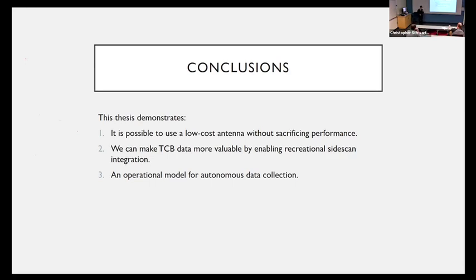We demonstrated that we can make TCB data far more valuable by integrating a side scan component and providing the opportunity to generate images of targets on the seafloor instead of only collecting single beam soundings. And we demonstrate an operational model in which a hydrographic agency could upload a series of waypoints to a TCB data logger, and then the data logger may go and collect side scan imagery autonomously without any input from the vessel operator.